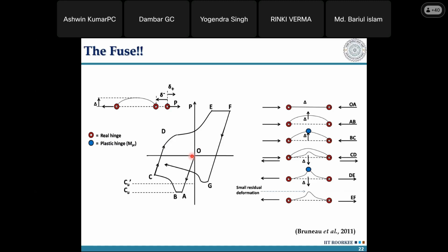Because of buckling, the only problem you have is that there is a load drop. It is going to buckle at a certain load. You already understand the Euler buckling theory, etc., for elastic buckling. So after a particular load is applied, it buckles from there. If this happens in the second cycle, it is not failure of the element, it is just buckling of the element, where the buckling capacity or the buckling load keeps on decreasing under multiple cycles.